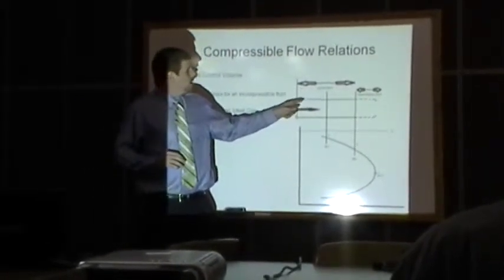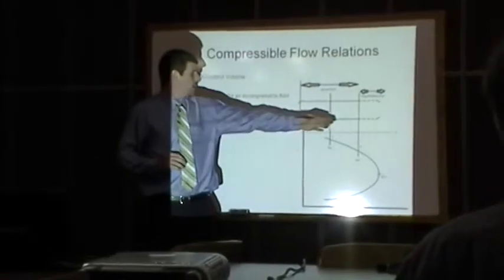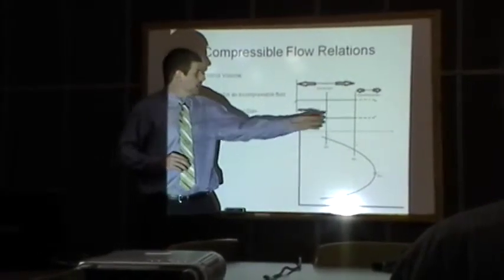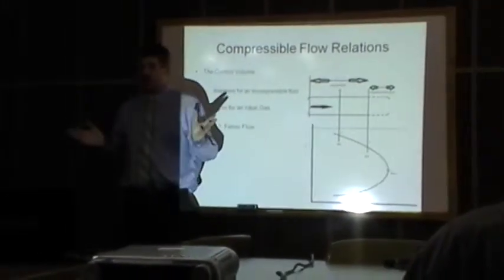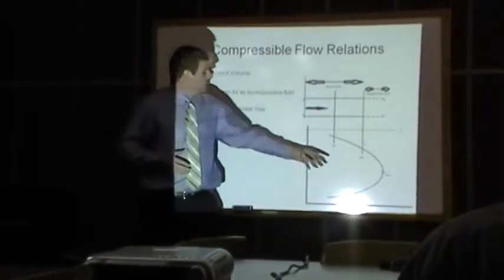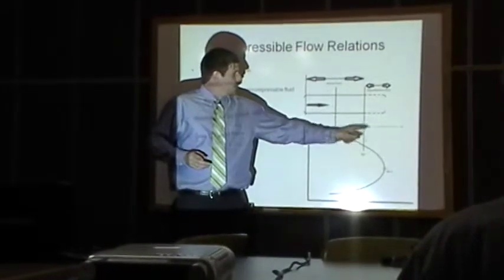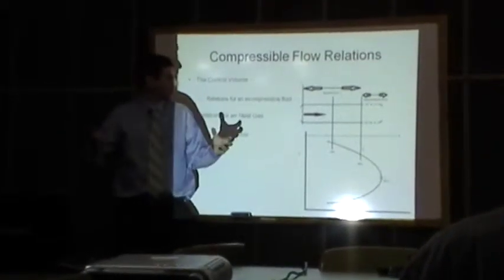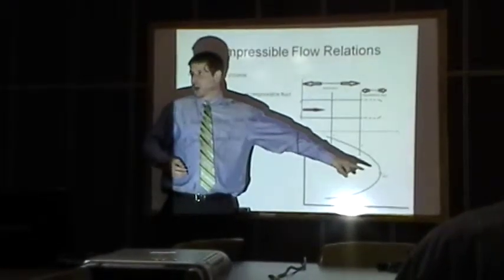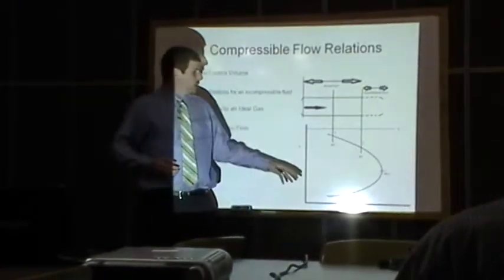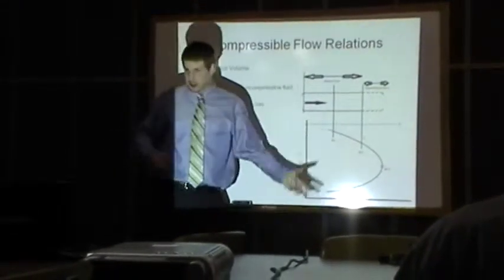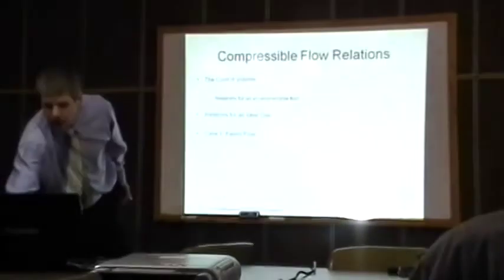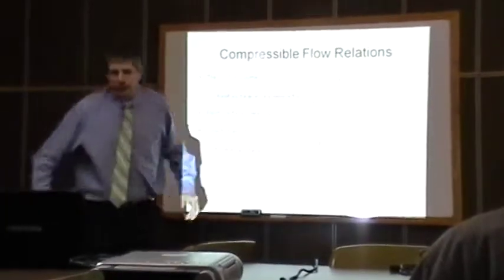Now, this is done with a regular duct. So if we have fluid flowing down a duct of any given length, it can be anything. To create this reference state, what we do is ask how much more length of pipe would be required to get it to this state of Mach equal to 1. And that's how these curves are constructed, and that's how the theory is constructed. So we can look at the relations for them.